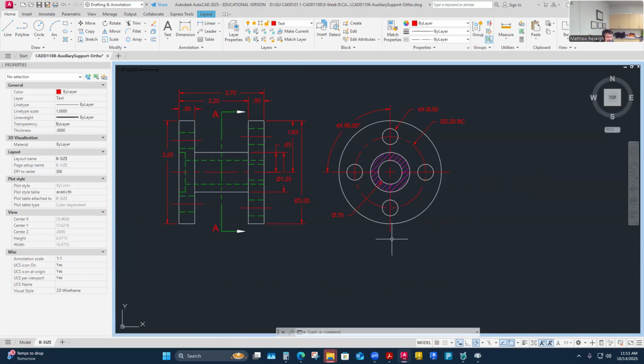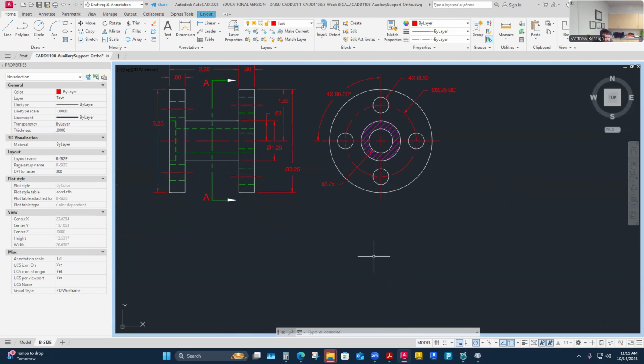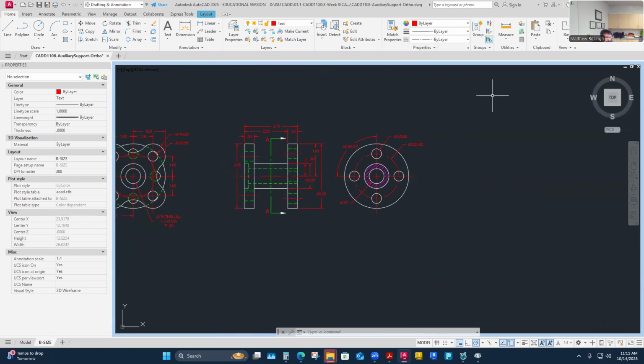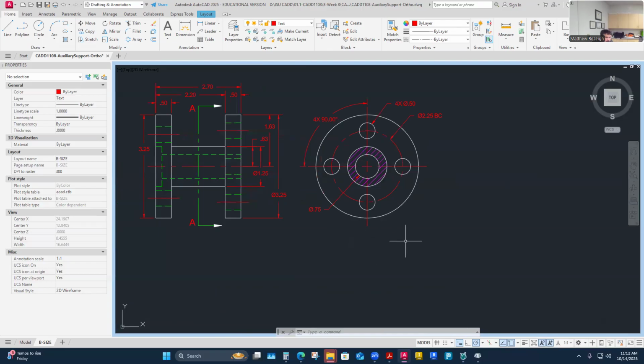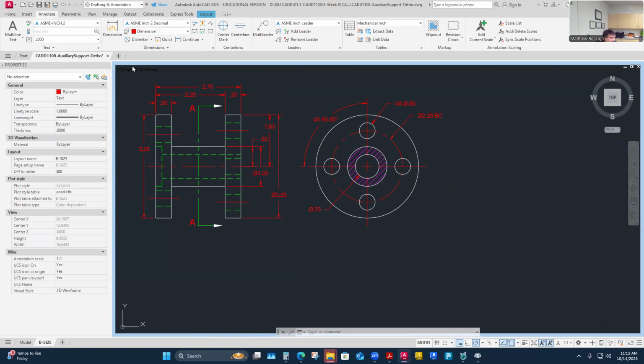I just need to identify that this is that section, right? I know I'm viewing that way from this. So whenever I would see this section pull up, no matter where it is on my print, even if it became removed and placed on another sheet somewhere, section A-A, I could always come back to this view and say, oh, I'm looking that way from left to right. Even though I've pulled this so it looks like I'm looking right to left, don't mistake that. Know that I'm looking left to right because my arrows tell me so. And that's how I would make sense out of it in case it was a dislocated view somewhere off on another sheet. Either way, it needs to have a title. That's how I can identify it.